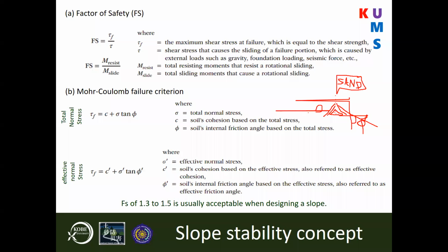So if you have sand which is very irregular, angular, that slope can be quite steep, like 38, 39 degrees. But if you have very, very round shaped grains, then the slope will be much lower, maybe 30, 34 degrees, very different. You would tell me 34, 38, not much difference. It is different. When you make the calculation, it makes a very big difference.